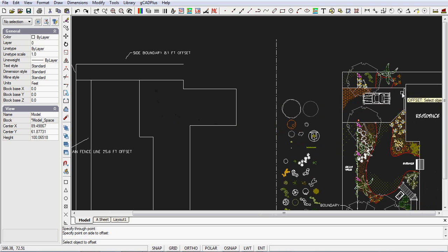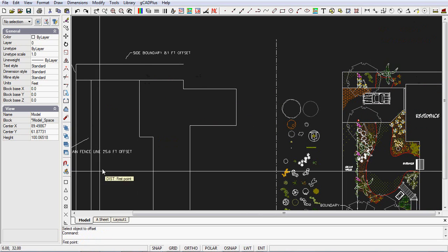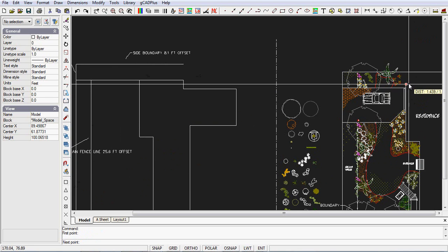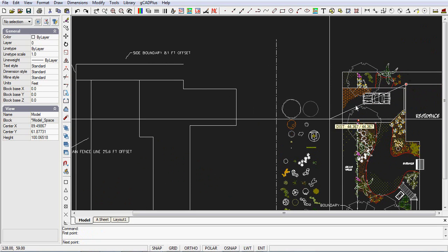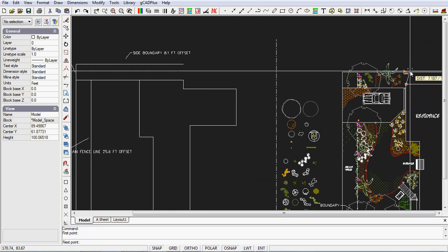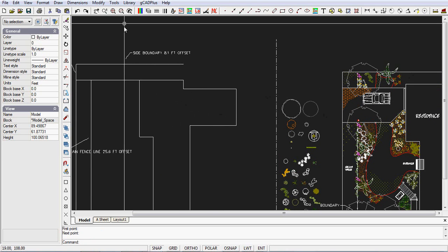And to me, there's obviously an error somewhere in our measurements. So what I'm going to do is just check. For mine, I was having some trouble. I need to check that distance again. So distance from that point of snap to the end of that one, and go perpendicular, I just missed, perpendicular to there, so it's 6.96. So I've made an error.